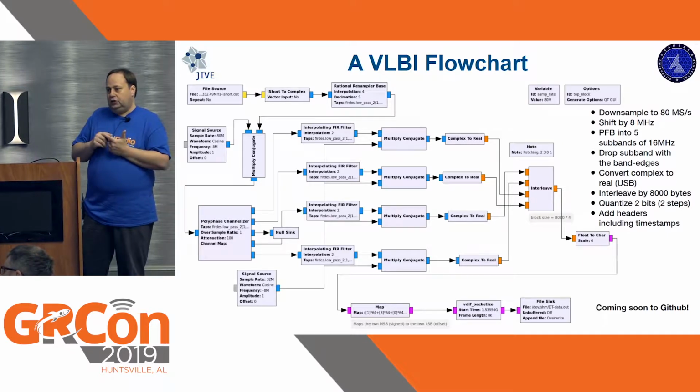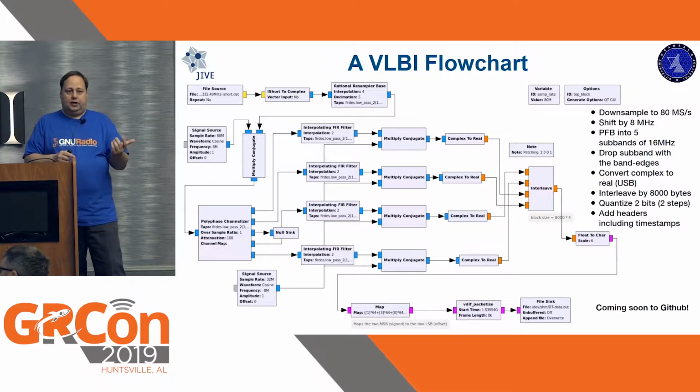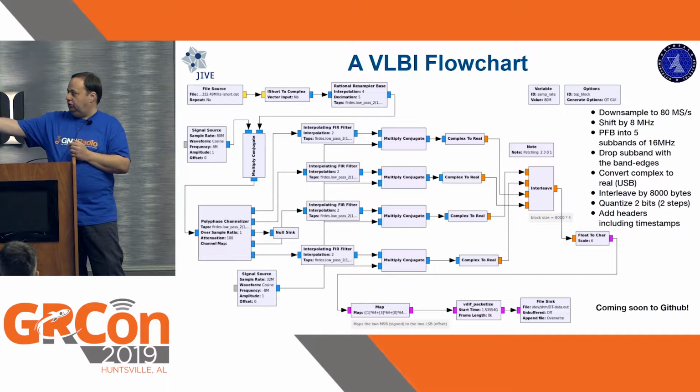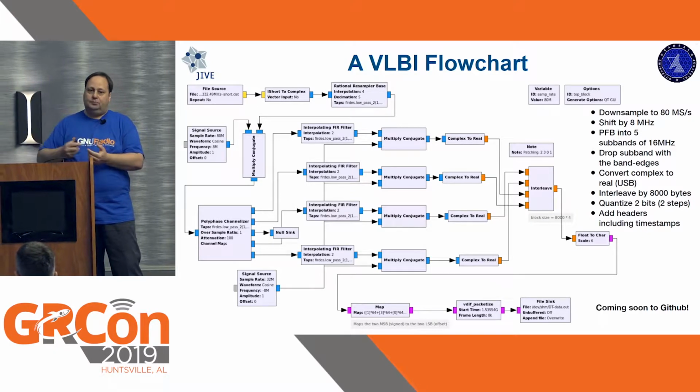This should have only been 1 block, but due to the bug I mentioned earlier, I'm actually doing it in 2 steps. Over here I bring it down to 8 bits, and then here I have a lookup table to go from 8 bits to 2 bits.